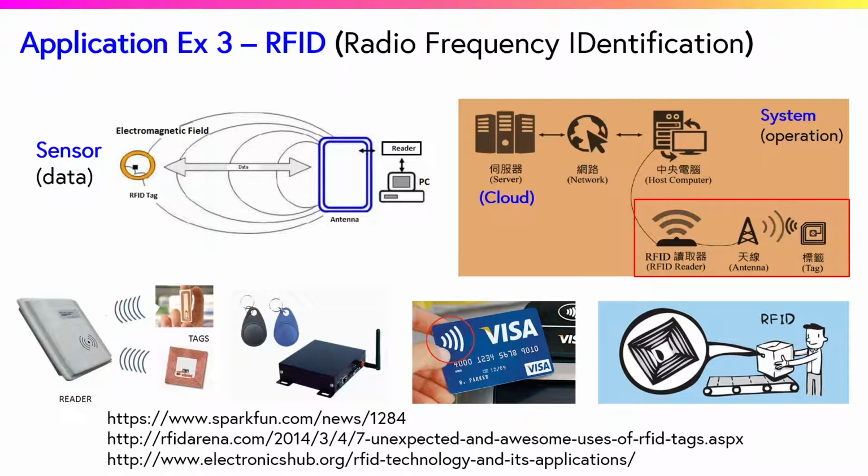So this is circular RFID. Basically, this kind of operation is passive RFID, no power. If we have a battery equipped with the RFID tag, that will be called active. The major difference between these two is the distance. For a passive RFID tag, the distance between the tag and the reader can only be 1 to 3 centimeters. But for active, it can be 10 meters, 30 meters, or even longer. This is the difference between RFIDs. This is the basic operation.